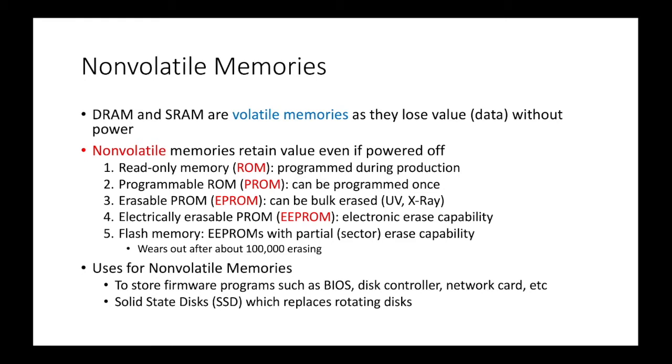Next gen electrically erasable PROM, EEPROM, has electronic erase capability. We had a breakthrough technology called flash memory, which is essentially EEPROMs with the partial erase capability. It wears out after a certain number of erasings though.